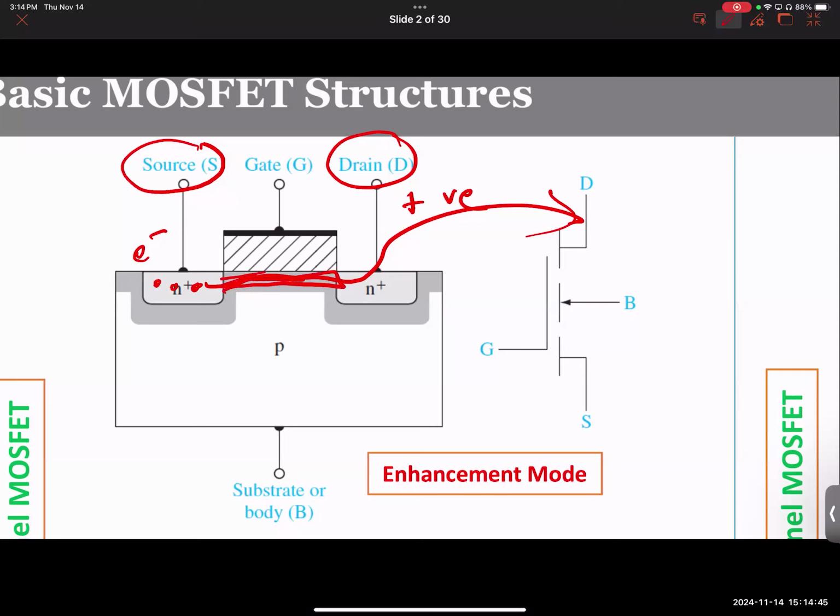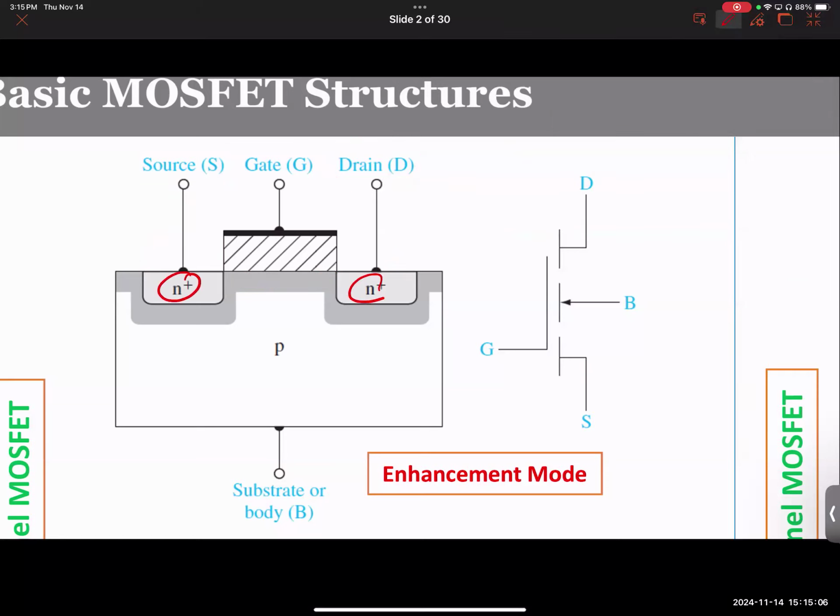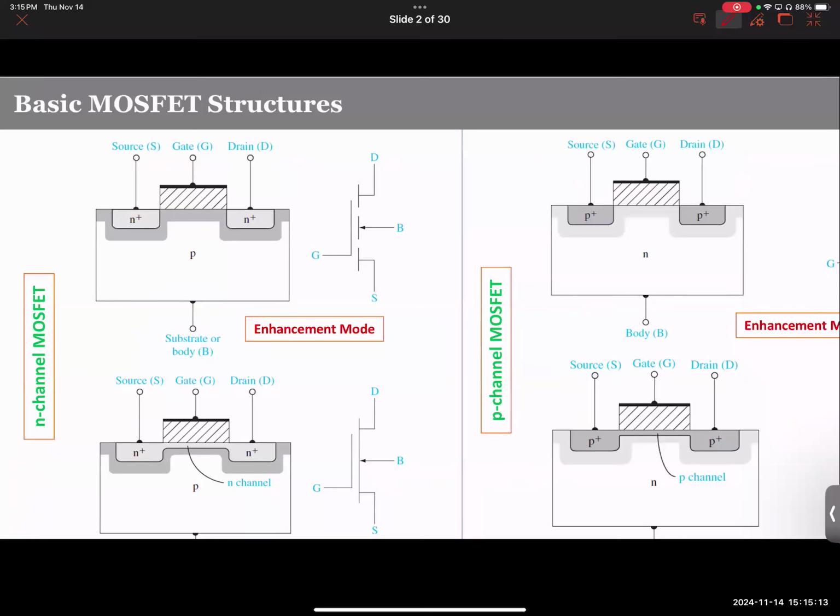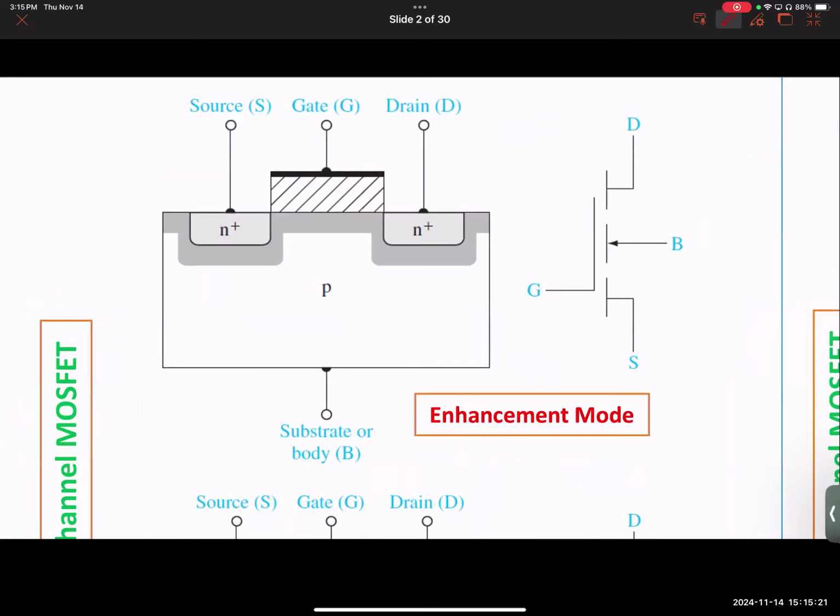If you have an N plus layer, that gives you less resistance, and it's almost like metal. They have no other purpose but to serve and catch electrons. Give me electrons, take electrons. That's it. So you need to make them as good a conductor as possible. That's why we have N plus or P plus material in that layer. Are you guys all good? I'm expecting questions at every step of the way, and please feel free to ask me. You are letting me go so easily.